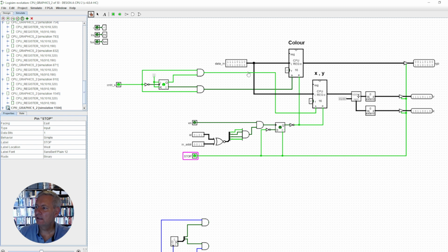Now, you can see that this data value comes in here and it just sits at this point and this point, but it only sits there for a small period of time, okay? It only sits there until a set value somewhere else in the circuit goes low. So when that set value goes low, this value here just goes to 0, okay? So we don't get any value. So it means that we have to time this properly so that whenever the set value for this goes high, it's now sitting in this state with the data in here. At that point, we have to do the control set.